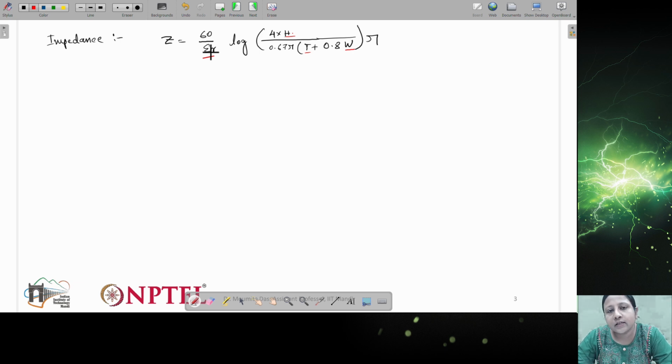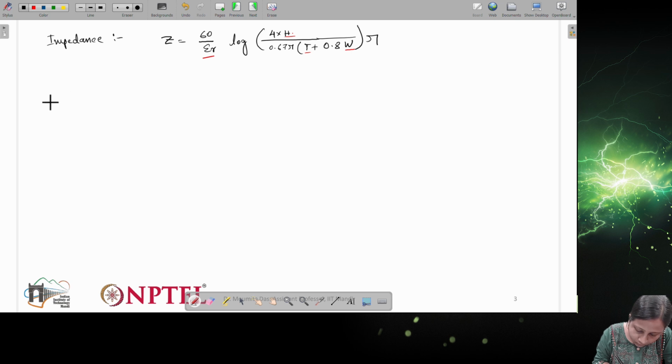Now this impedance needs proper termination, otherwise there will be noise traveling back and forth through this impedance. The termination can be done using different methods. These are the noises which can be present in the board itself, and at high frequency the effect of the noises will be more. So we need to provide a way to reduce these noises. To reduce these onboard noises, what do we need to provide? Onboard noise reduction.